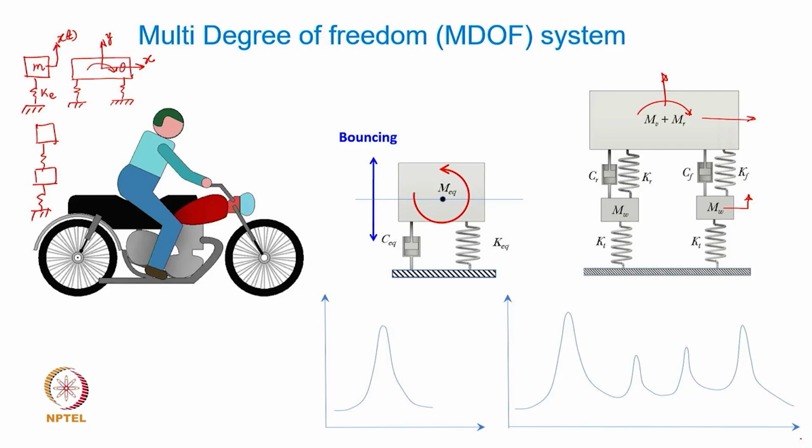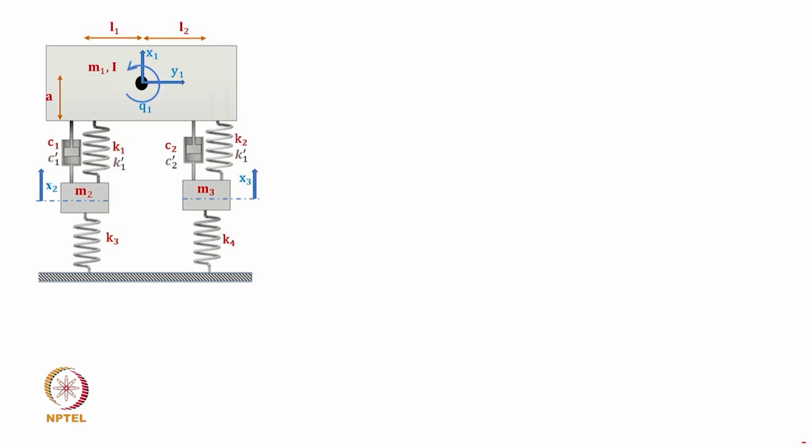So, that is what is going to be the obvious character of a multi degree of freedom system. You get to see multiple resonances, and so it is important to know these frequencies accurately, so that you can use your operating speed range reasonably away from the major resonances. Okay. So, therefore, eigenvalue analysis or finding natural frequencies is the first step in the design process.